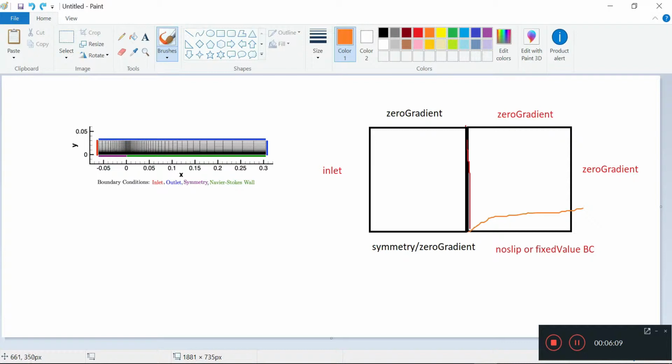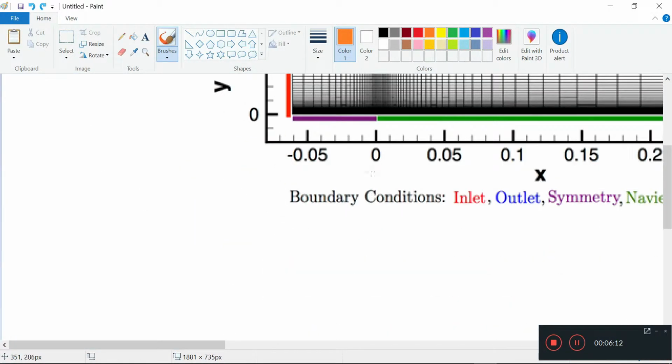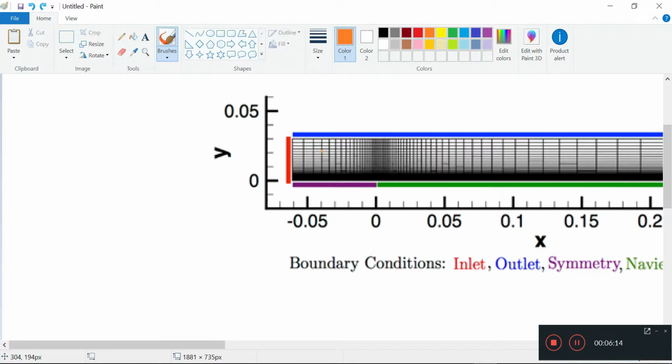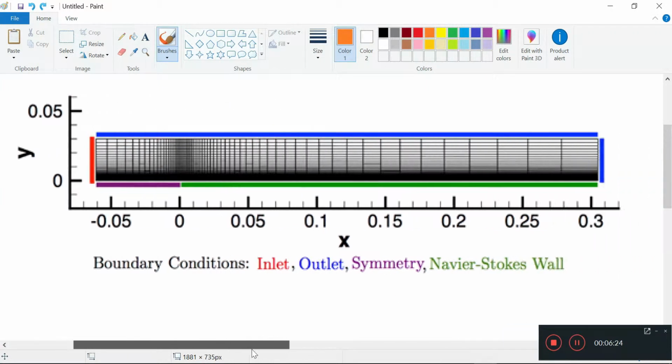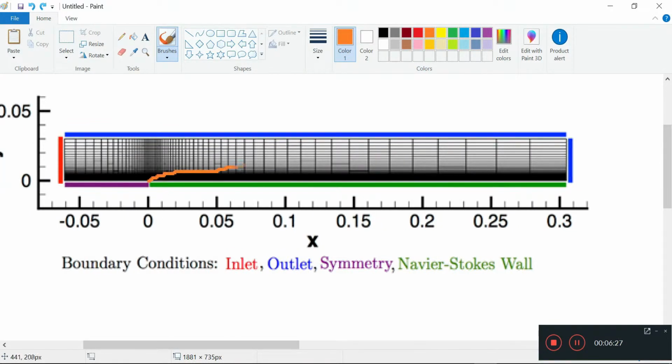And if you notice, the mesh here isn't exactly uniform throughout. The mesh size here is significantly bigger than, say, the mesh size here. Now, why would you want to do that? Well, most of the action happening in the boundary layer is usually along here, right? And down here there are lots of interesting things happening, whereas over here things are more predictable and not as interesting.